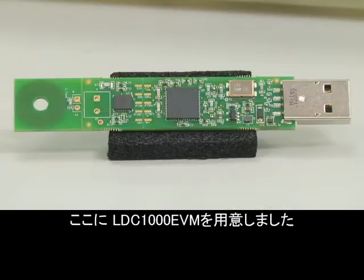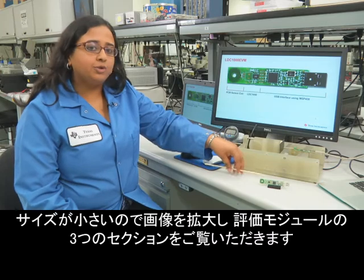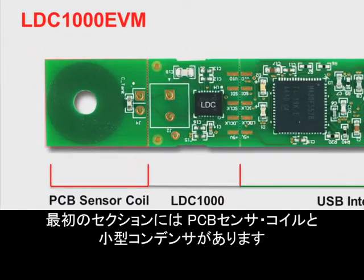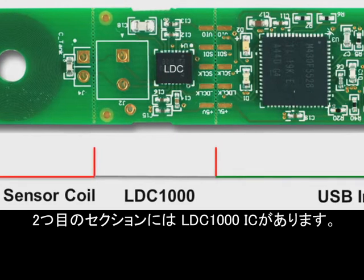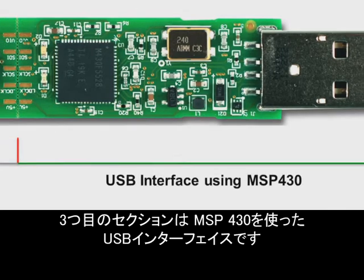To get right into it, the LDC1000 EVM is displayed here. Due to the small form factor, I'm going to take you to a larger image to show you the three different sections of this EVM. The first section has the PCB sensor coil along with a tiny capacitor. The second section has the LDC1000 IC. The third section is simply a USB interface using the MSP430.